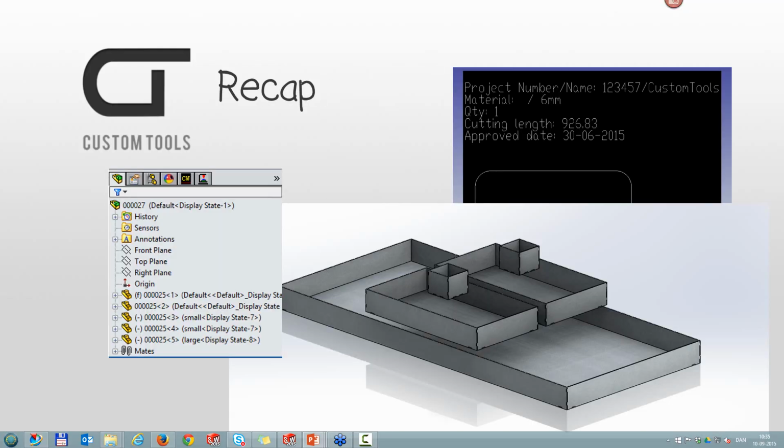Okay, so a small recap again. You can process an entire assembly and sub-assemblies. You can define if you want merged DXF files where all parts are combined based on material thickness, or you could create individual DXF files for every single sheet metal component found, including the multi-bodies. The file name can be defined very flexibly and you will always have the files that are up to date and accurate. The merged DXF, for instance, send that to a subcontractor with the files packed with information like the quantity used or the total cut length required per DXF, and you will have a quote back in no time.